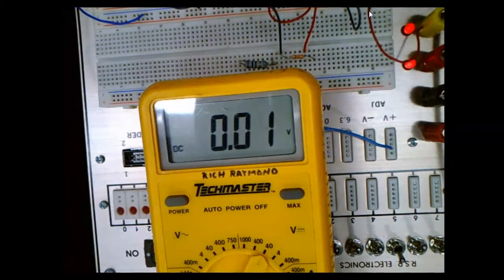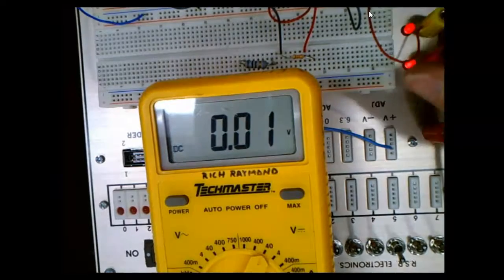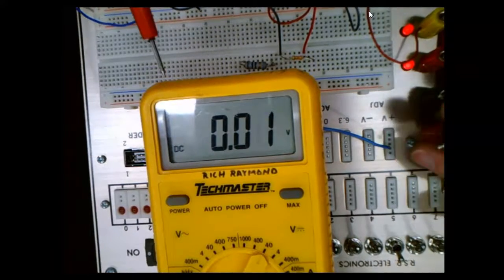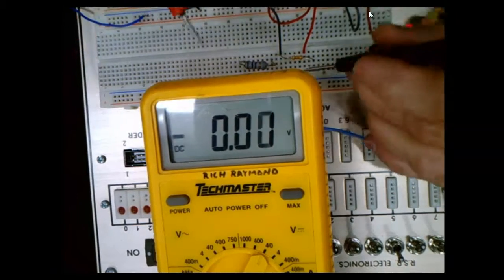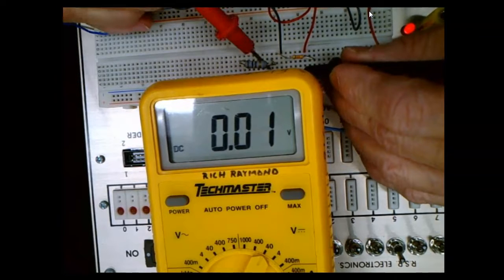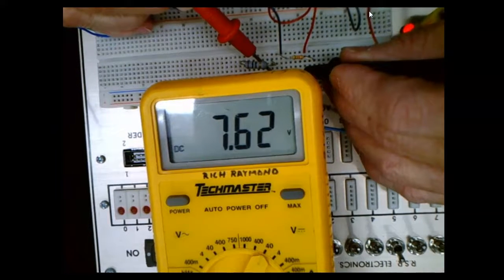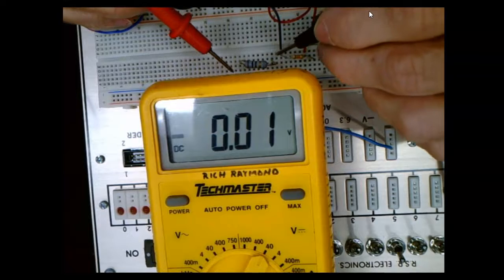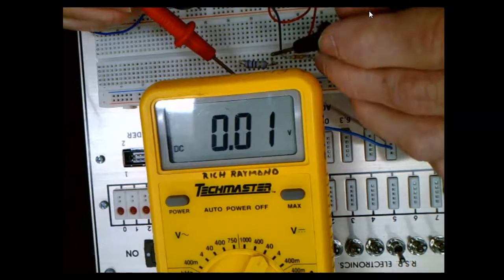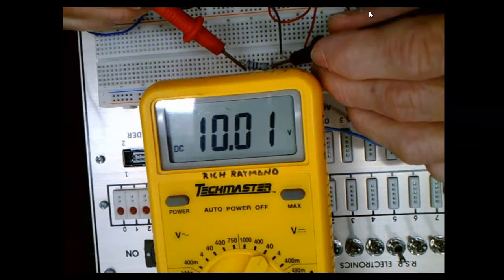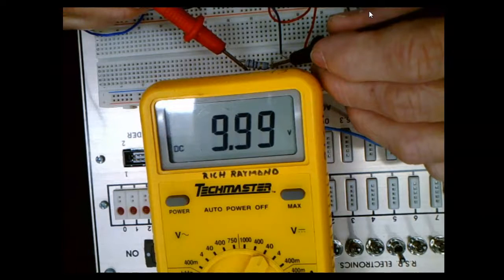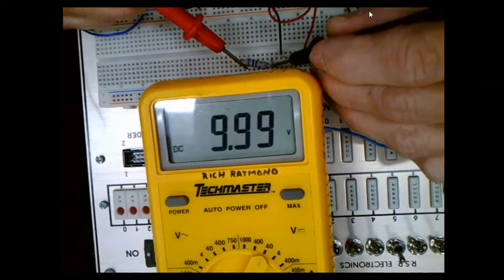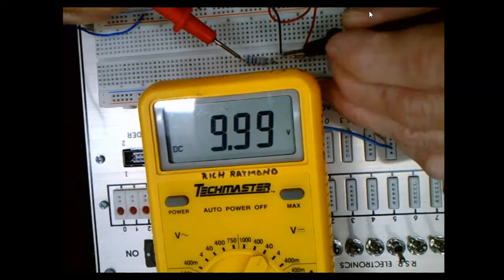Okay. Now I thought we could get 12 volts out of this, but we're getting 17 volts out of here. So here's my voltage collector to emitter. We can't get 8 volts, right? Okay. And I'm going to come over here and look across this resistor now. It's measuring 10 volts. So my base current has gone wild, right? You have to be real careful because the transistor's going.